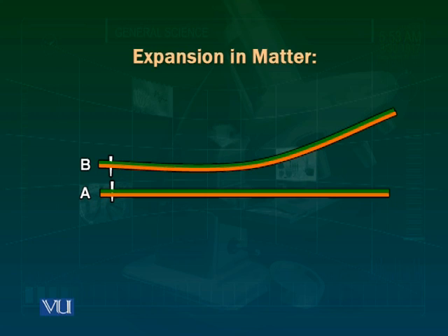However, brass, because it expands more, is going to expand more. So when the outer side expands more, it is going to bend the strip in a particular direction. And because of this bending, this strip has the capacity to exert a force. This force which is exerted is then used to make or break an electrical contact.